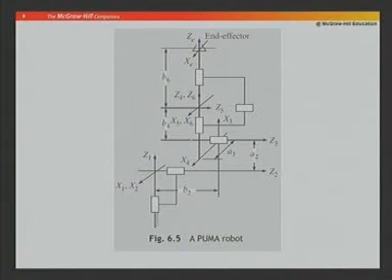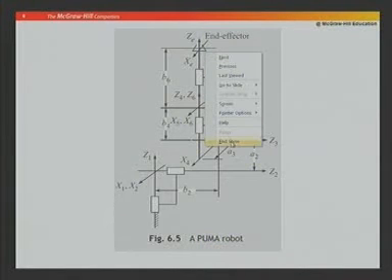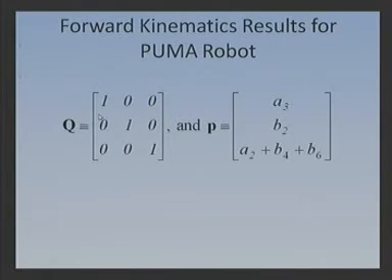Obviously, if x 1 and z 1 are parallel to x e and z e, y 1 should be parallel to y e, and you get this identity matrix. If your calculation does not show an identity matrix, but from the physics or the geometry of the manipulator they appear to be parallel, then you have made some mistake somewhere. That is one way to debug your results.